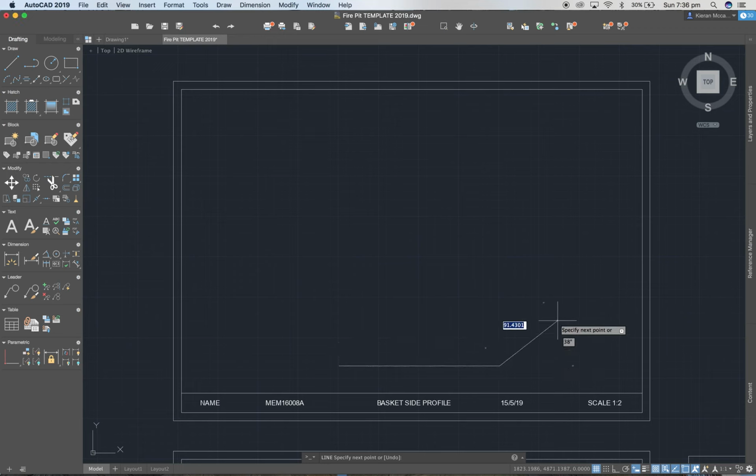And when I'm happy with those two sizes, I can press enter, and that will give me my line. Now to break the second part of the line, we just press escape, and again we go back and select that line tool. When we hover across the middle, we're after the midpoint, and you'll get this green triangle here. We'll highlight midpoint. I'm going to select that, and I'm going to go up the way, and the distance we want to go is 300, and again we want the angle to be 90, which we've got there, which is perfect. And we're just going to press enter there. Now at the moment I don't want to cancel the line, so I can carry on, and I'm going to go 200. Again, that is going to be 0, and then I'm going to finish it off by bringing it back down here. And when it snaps to the end point, we'll have that green square, and we can select that and have it like that there.